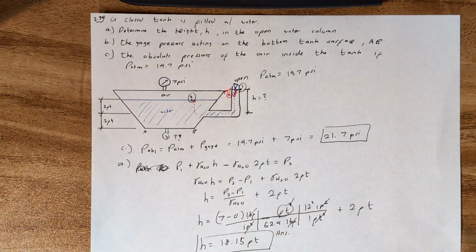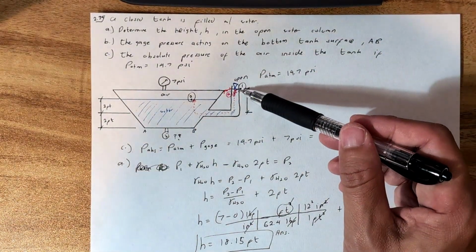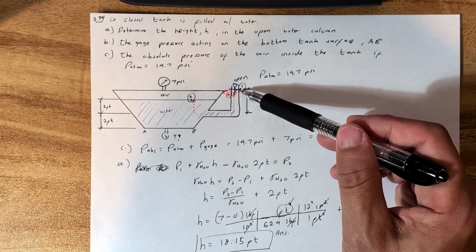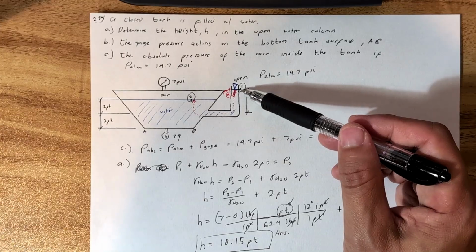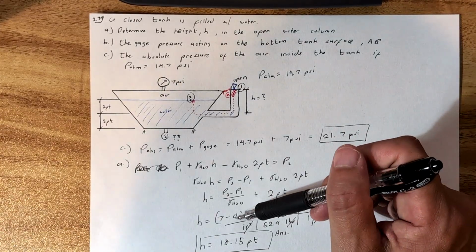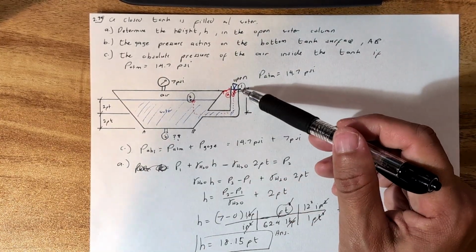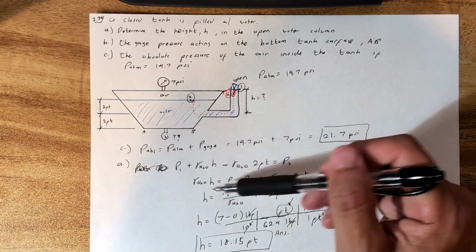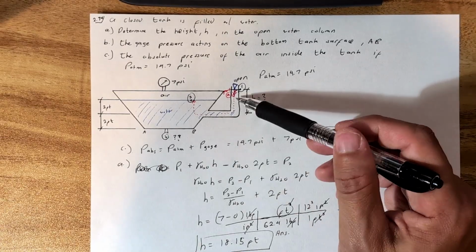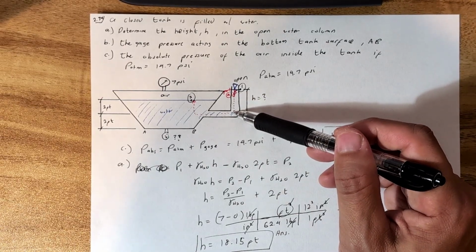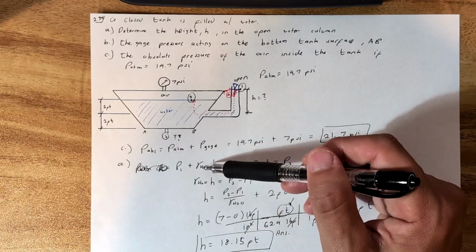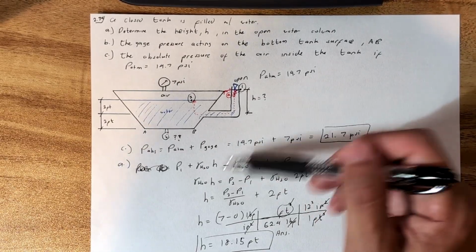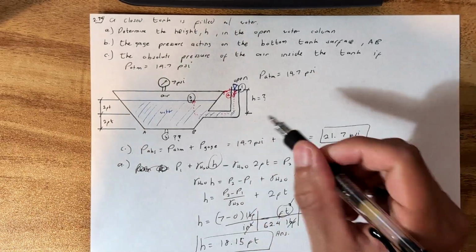So just to recap part A. We're swimming from point 1 to point 2. At point 1, the pressure gauge is 0, which is what we got right there after solving for h. So from P1, you're going to swim all the way down, and this is positive because the pressure is increasing as you're going down this pipe right here. So it's positive, specific weight of water times the height, which is what we want.